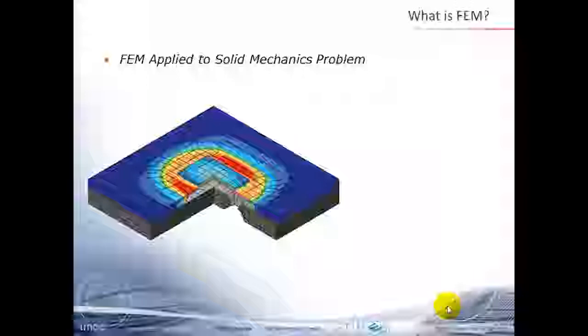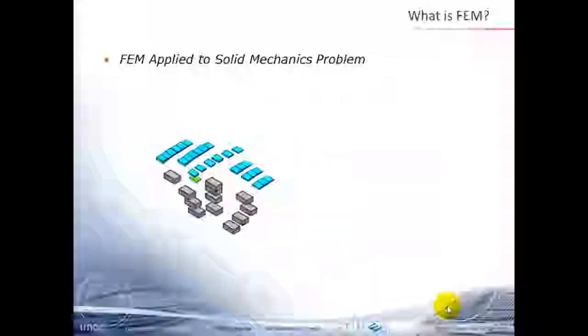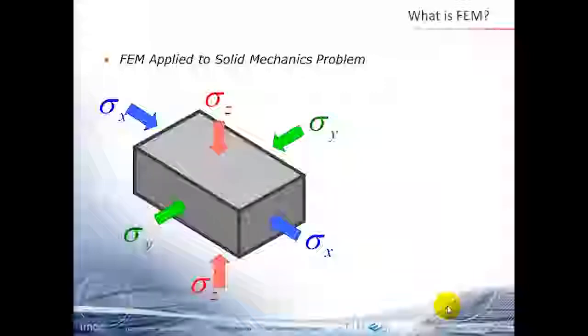What is finite element actually? With this example of the mechanical domain, I try to explain this. Just assume that you have a kind of sensor, it is already meshed. I'll take some of these elements, I'll separate them, and I just look at one. And just like in physics, where you can describe your forces on an infinitesimal element, we now describe all the influences on a finite element.